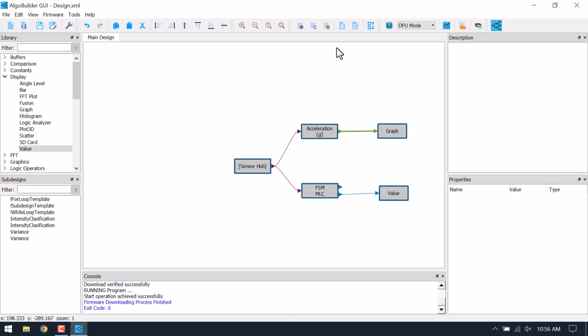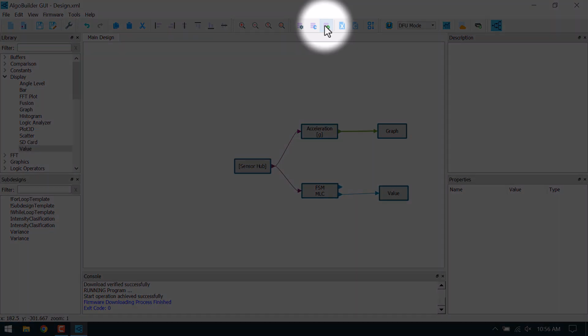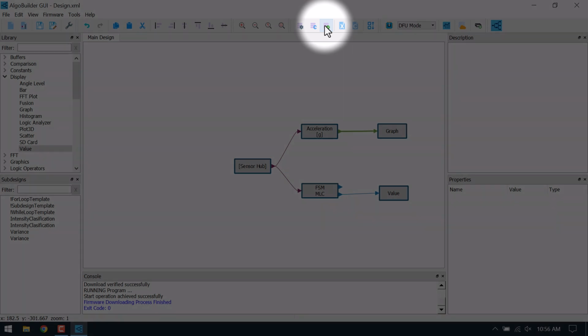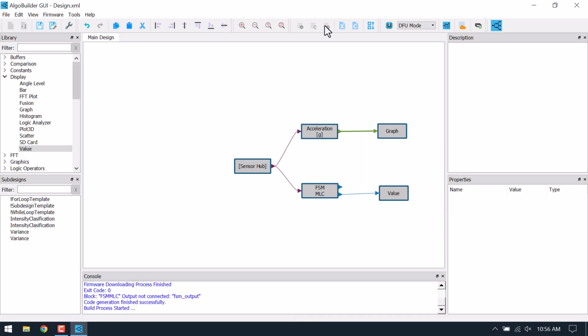Click the Build Firmware icon. This should be a quick process since only a few source code files will have changed. When the build is finished, you should see a message that the build process finished with 0 warnings and 0 errors. Program the firmware to the board once more by clicking the Program Target icon in the toolbar.